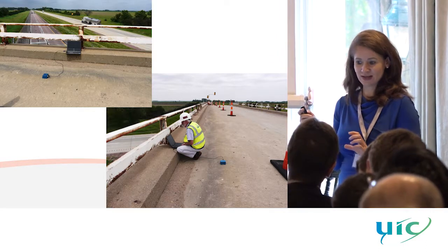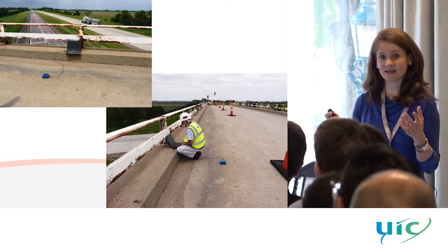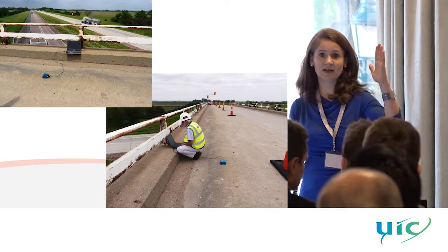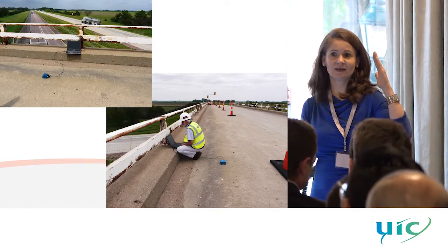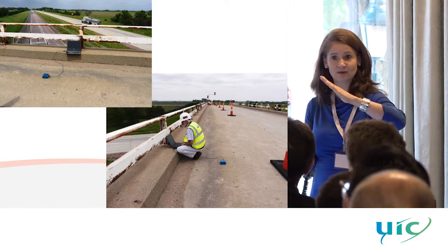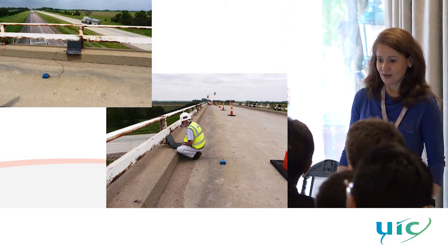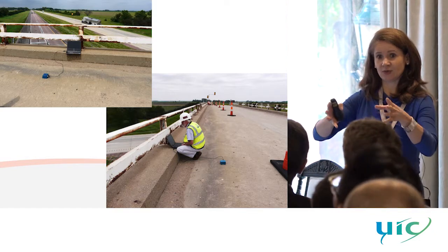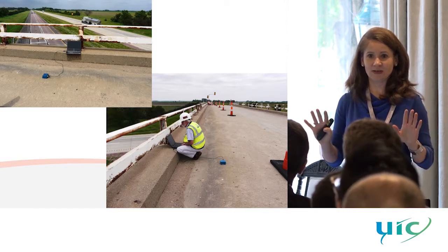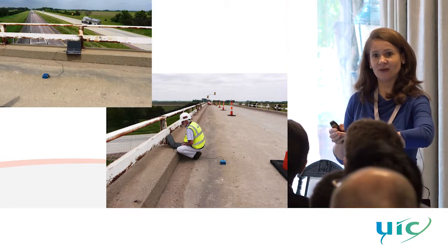We have been using this particular accelerometer because of its sensitivity. It was developed for structural purposes, for monitoring walls after earthquakes, to see if they're still moving or if they are stable and safe to enter the building. The principle is to put the accelerometer on the bridge for 8 minutes without any loading and rely on the background vibration.